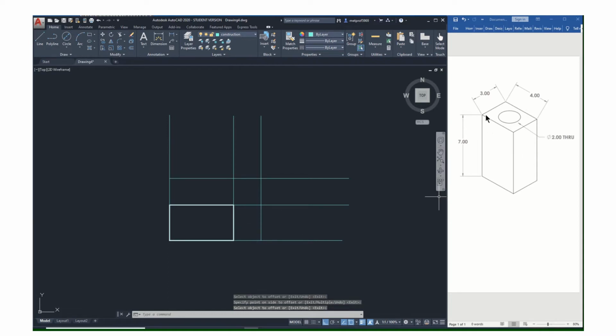So now if I'm drawing the 7 by 4, the depth of the part then is going to be 3 inches. That's the other dimension that I have, again, just because I've chosen this as my front view. I know it's a little confusing perhaps, but hang in there, you'll see how that works. So that means I need another offset of 3, enter. Now, it just so happens both of these are 3, but that shouldn't be a problem. Let's see what the top view looks like.